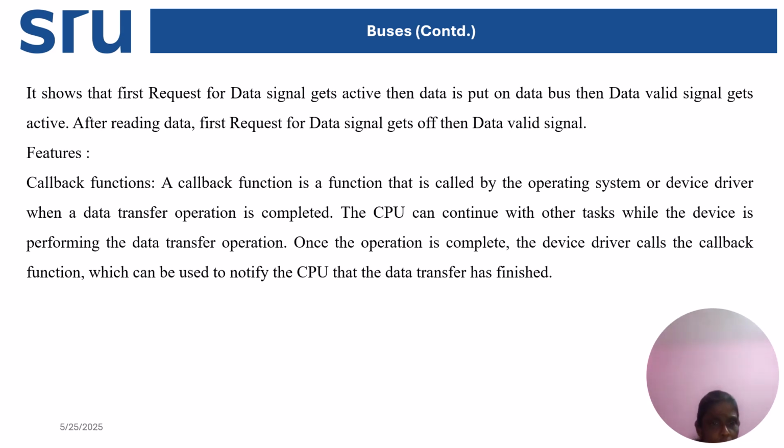Now, what is a callback function? It is called back. The function is called by the device driver when the data transfer operation is completed. Whenever the CPU is performing the main task and in between data transfer is required, an interrupt happens. For that interrupt, a calling function, the callback function, is given.